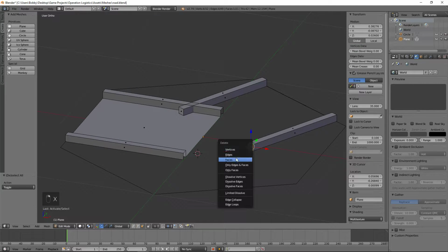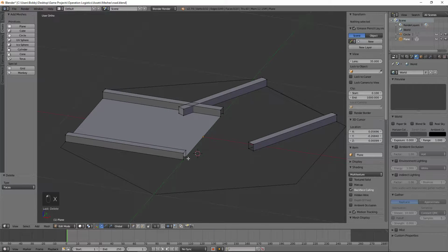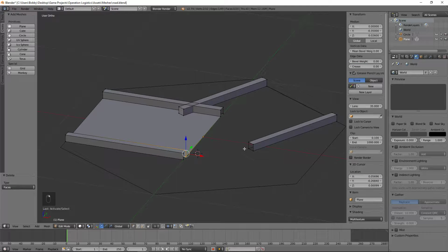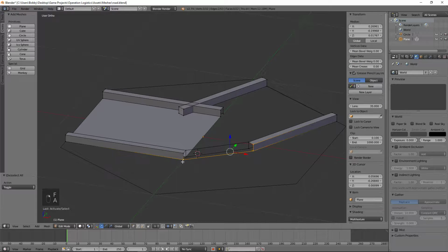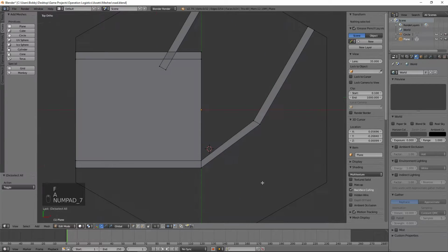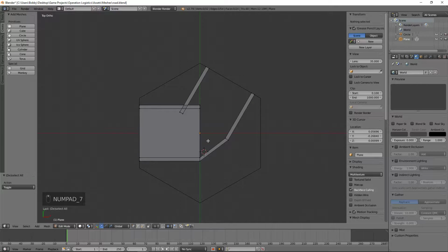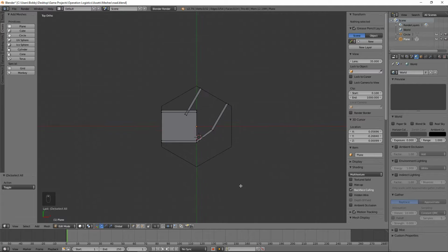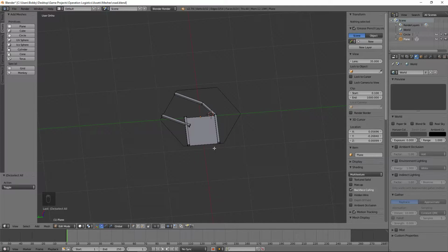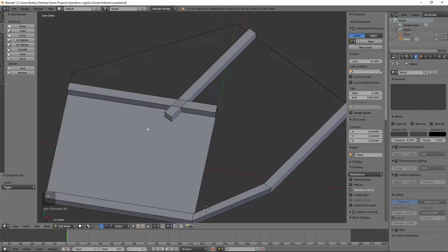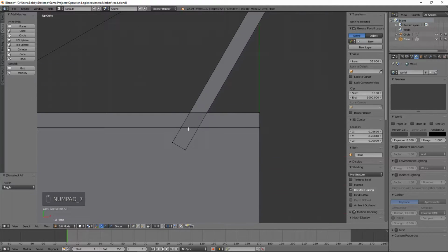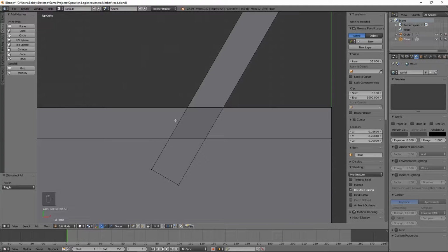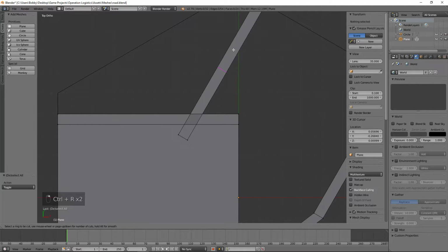We don't need a face here, so I'm going to go ahead and delete that face, and then I'm going to grab these vertices and put that in there. These vertices down here, just make this curb over here. And that makes this corner on this side. Now this is, of course, not the sharp corner. This is the slightly smoother corner. And then we're going to need to go ahead and create a few vertices over here for this little pattern. So I'm going to go ahead and create an edge loop around here.